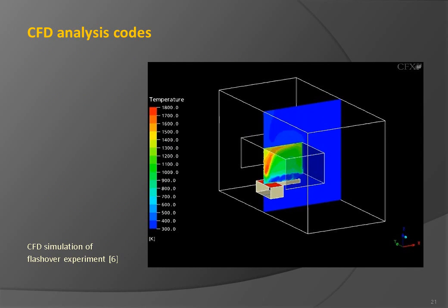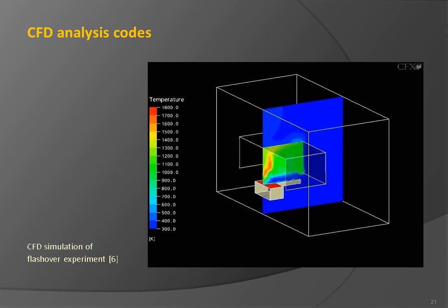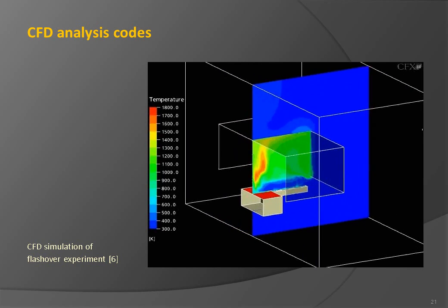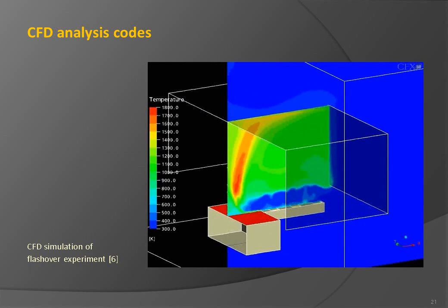The animation shows a flashover experiment where wood pieces are ignited due to thermal radiation. Due to symmetry, only one half of the experimental setup was modeled. It consists of a propane burner under the metal hood, which helps to create a stable hot layer of combustion products. Below the hot layer, 3 pieces of wood were located away from the central burner.